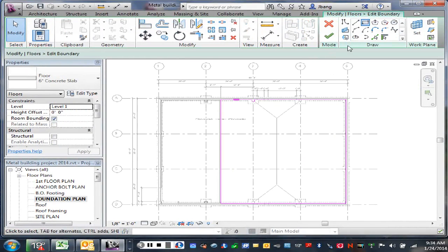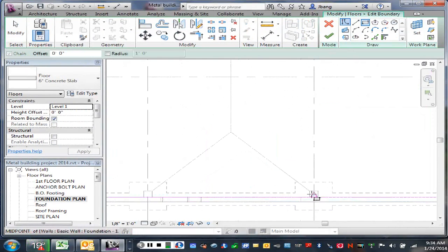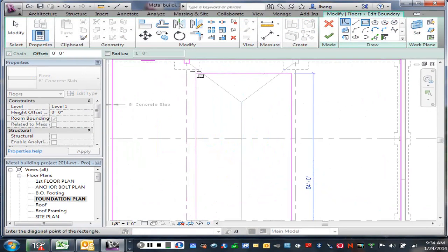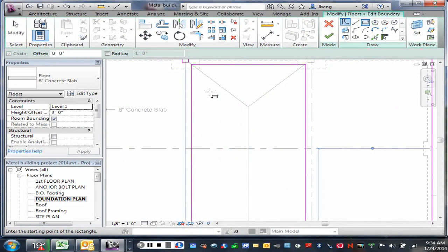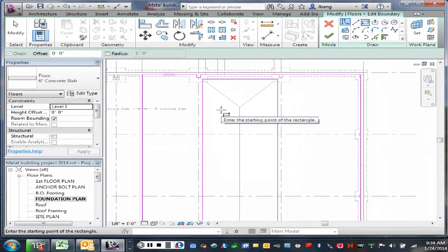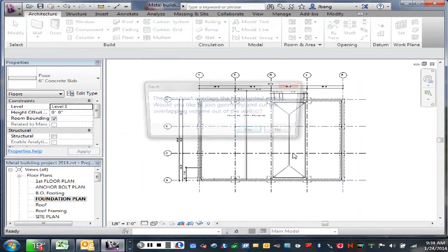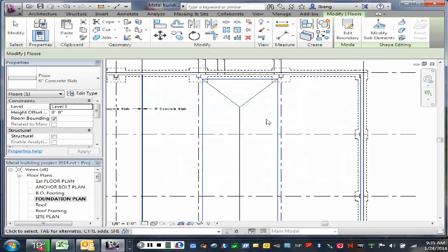and we're going to go to a rectangle, and I'm not going to lock onto that corner. I'm going to lock on up from that corner a ways over here, because if I locked onto those corners, I'd be attached to the outside boundary, and you can't cut a hole if you're attached to the outside boundary, right? So basically, by creating that new border within there and saving that, I now have a slab that has a hole in it.